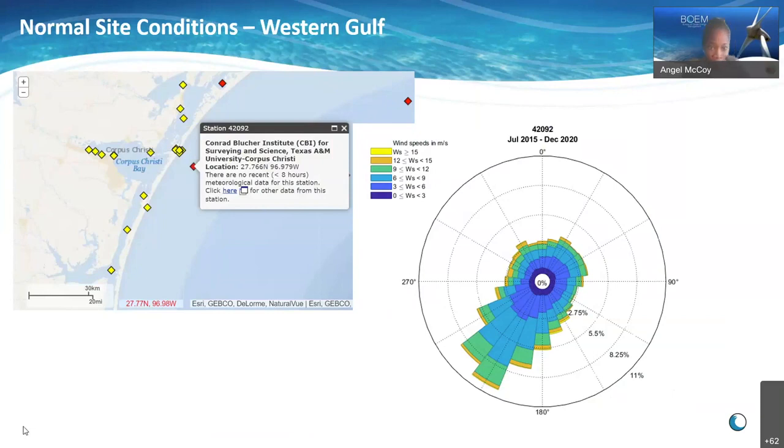And as we look at this wind rose, it's showing us the frequency of direction of wind speeds, but I don't want you to put much weight in the value of the wind speeds as noted here. Because this is coming from a buoy, the speeds that are measured are about 3.4 meters from the sea surface, or about 10 feet from the sea surface. So that doesn't necessarily correspond with the wind speeds we would see at the hub height of a wind turbine. But this is good for helping us to understand just the direction of the winds that they're traveling and that they're coming from.